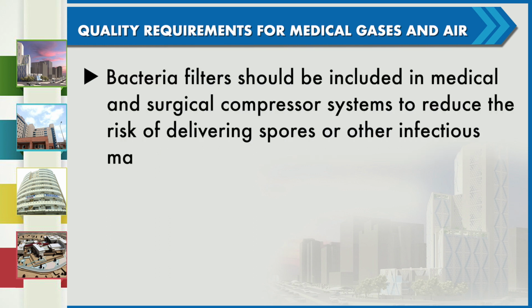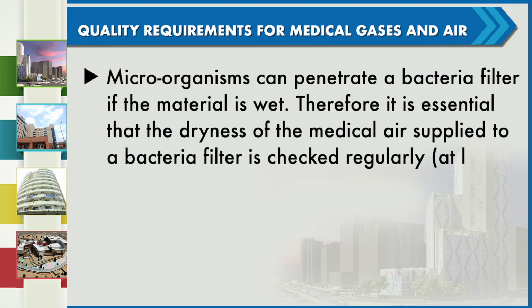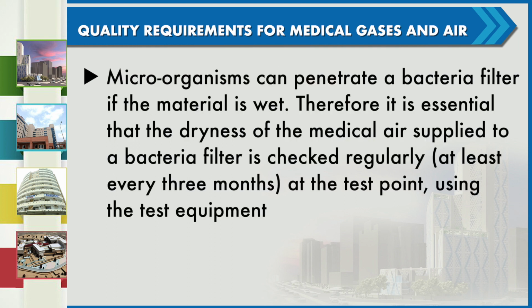Bacteria filters should be included in medical and surgical compressor systems to reduce the risk of delivering spores or other infectious materials to vulnerable patients. Microorganisms can penetrate a bacteria filter if the material is wet. Therefore, it is essential that the dryness of the medical air supplied to a bacteria filter is checked regularly and at least every 3 months at the test point using testing equipment.